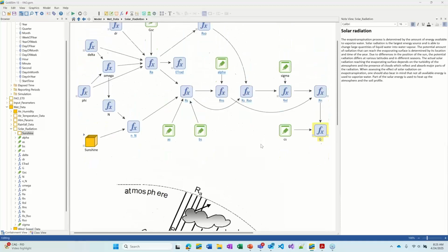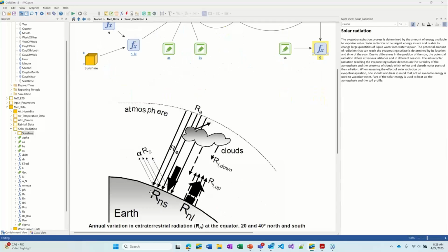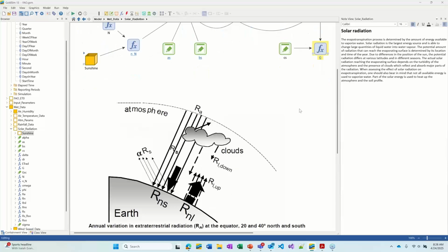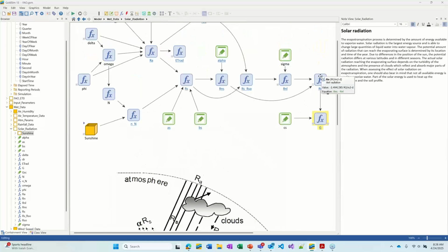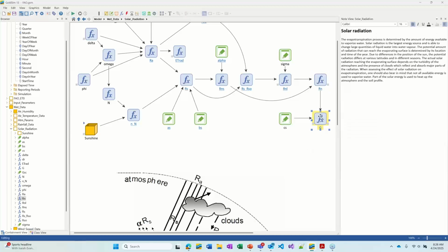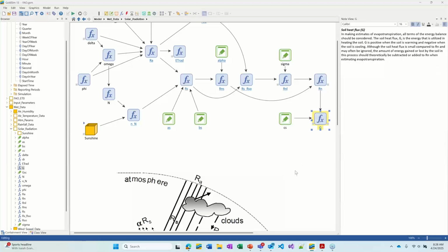Okay, so from that point, we're able to capture the remaining parts of this energy balance, and we end up with this Rn, which is the main driver of evapotranspiration. Now, I was mentioning earlier the effective soil depth and also the previous value of the temperature, and that plays a part here in this thing called soil heat flux. And this is what I was talking about, how sometimes this is set to 0. In fact, the document even says, for a larger time step, like a daily time step or a monthly time step, perhaps just set this to 0.